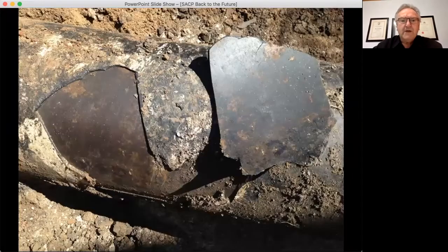What about pipelines? Here is a photograph of a pipeline with a bitumen coating, and these coatings were very prevalent in large parts of the world, particularly in South Africa, for many years. They've largely been superseded by other coatings which have better electrical resistance characteristics, but there are many thousands of kilometers of bitumen-coated pipe all around the world. Can we use a sacrificial anode cathodic protection in this situation?